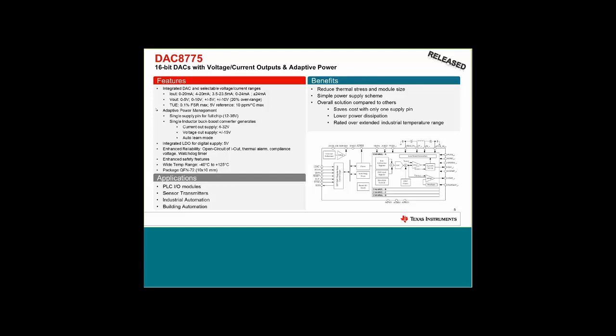Yeah, the only way that we might be able to detect some kind of coil burnout, again, all we're trying to do is measure the effective current that we're delivering to the load. So if it became an open circuit condition, we could detect it. If we hit compliance conditions, we could detect it. But otherwise, it would depend on exactly the nature of the inductive load failure for us to have the capability of actually reporting the failure.